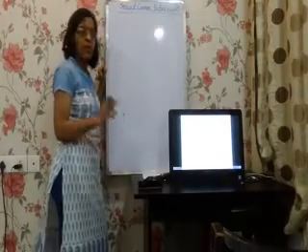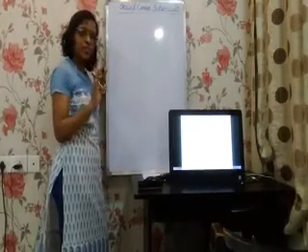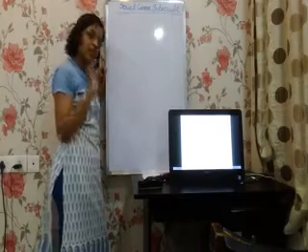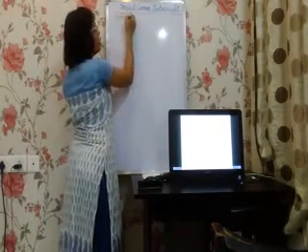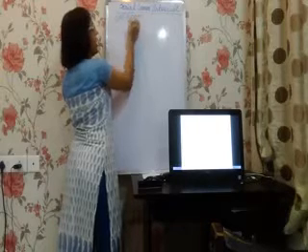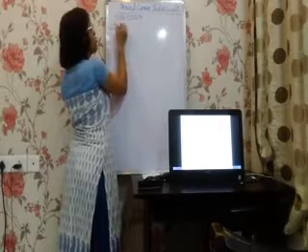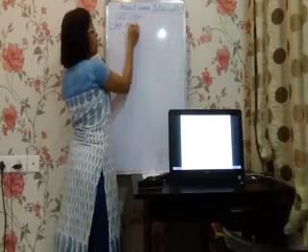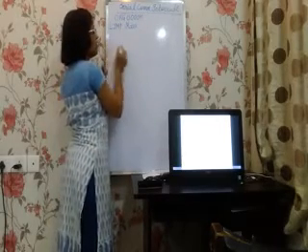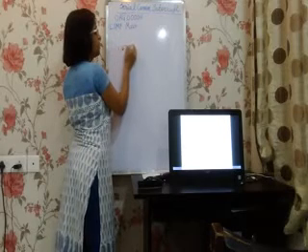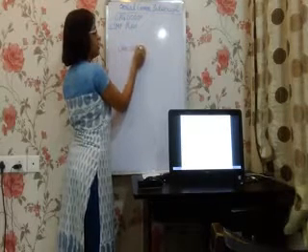For the program, all the prerequisites we have already written. Now let us start with the program directly. I will give ORG 0000H and LJMP main. This is what we do always. Now in the main program, I will always start from the address 0030H.